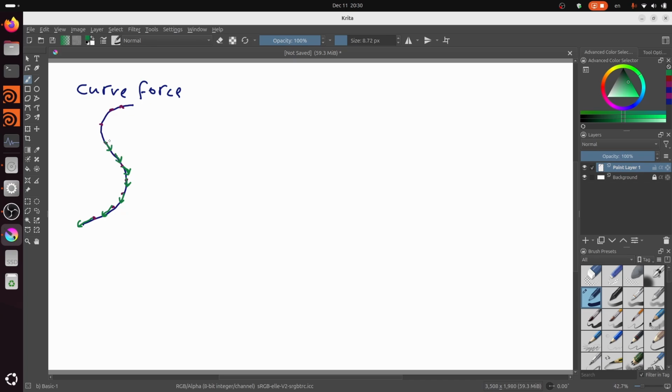And we are going to set these vectors as the normals. So these are going to be our normals. We are going to create normals that are tangential to our curve like this. And what we are going to do next is create a volume with the same bounds of this curve.